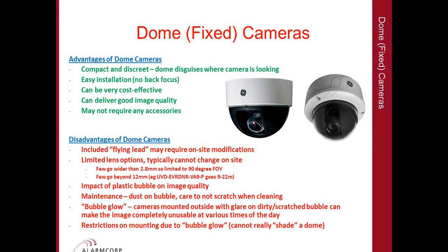Maintenance. Once you start to get dust on the bubble, fingerprints during commissioning, or grime building up, you do need to clean it because that is going to degrade the image quality. And of course, cleaning a plastic dome is like cleaning plastic sunglasses. You do need to take care, otherwise you will put very fine scratches into the bubble, and of course that will have a negative impact on image quality as well. So possibly domes are not always the best choice in an environment prone to fast grime or dust buildup.